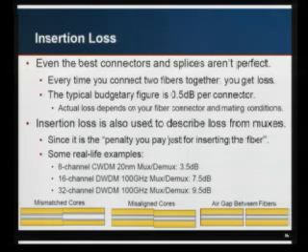And the typical budgetary figure for a connector is 0.5 dB, and it may be less or it may be more. It depends on what type of fiber you're using, how clean the data center is, how nice the connectors are.